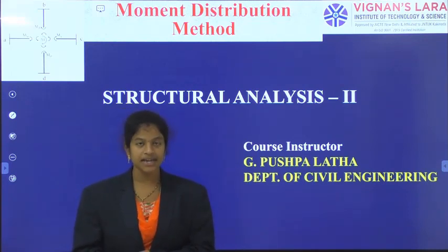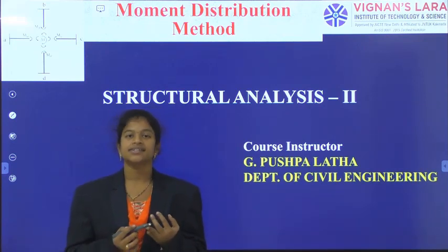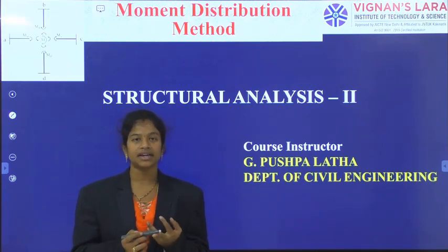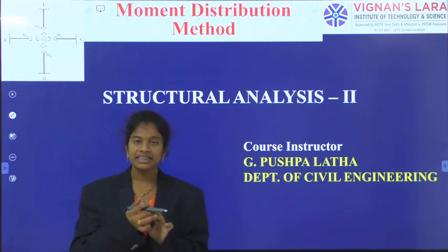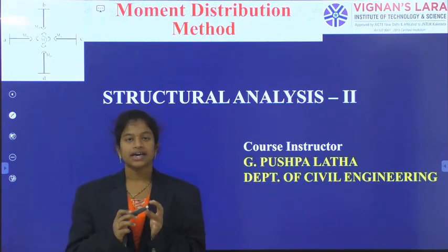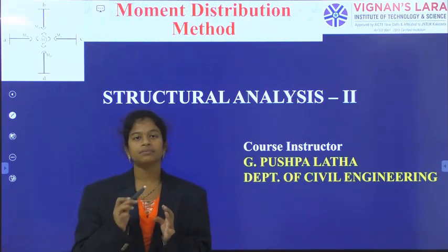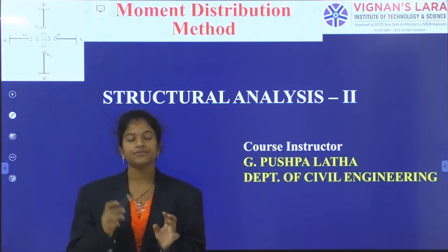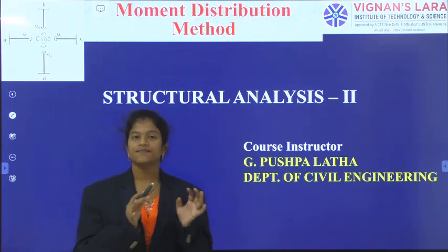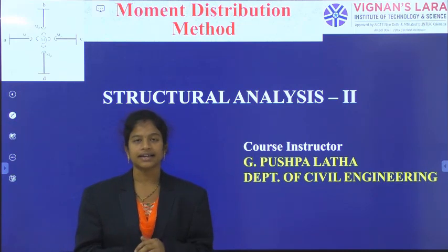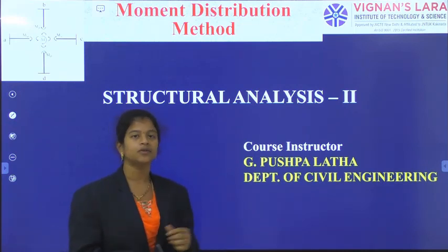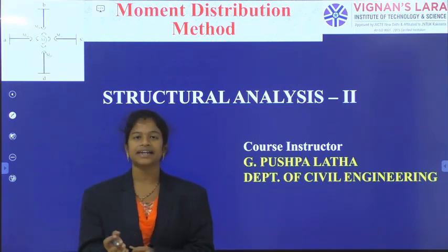As we have already said, the overall analysis involves the calculation of support moments, calculation of support reactions, generation of the actual bending moment diagram and generation of the shear force diagram. The remaining three steps, support reactions, bending moment diagram and shear force diagram, will be the same for any method we use. But the first thing is how we calculate the support moments. Here I am using the moment distribution method for calculating the actual support moments occurring.